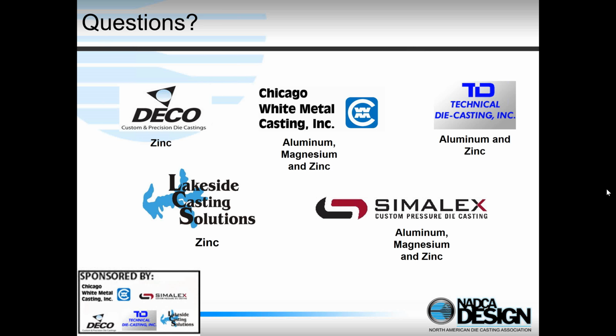Every time you make a casting, you heat the die, you eject the casting and spray the lube on it, it cools the die. So this heating and cooling gives us a tensile and compressive load on the surface of the die, and ultimately it starts to crack. And depending upon your casting, if it's a real cosmetic part, then you probably need to replace it at that time. If it's hidden away somewhere, a lot of customers will allow the caster to keep on casting for a while, but ultimately it's going to fail.